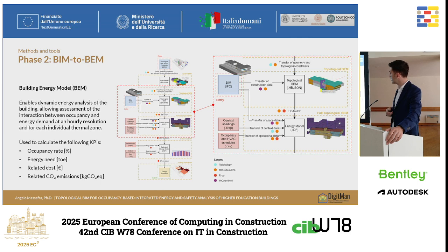And then we took the same BIM model, in the IFC format, to translate all the data related to the construction, the spaces and the zones to the energy model. At the end, the energy model is converted to an EnergyPlus model. We add more information about context, shadings, and occupancy and HVAC schedules.